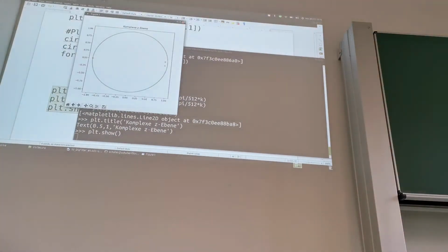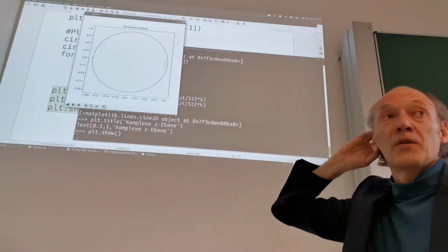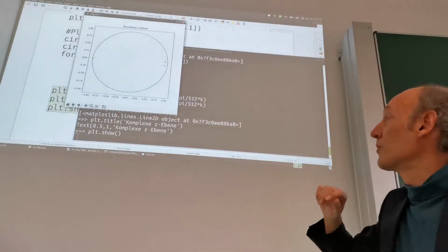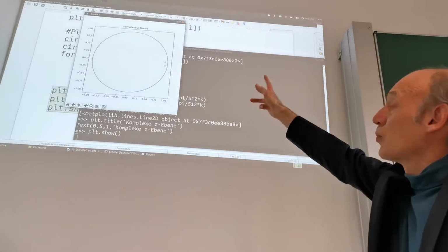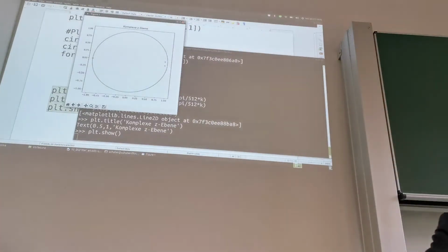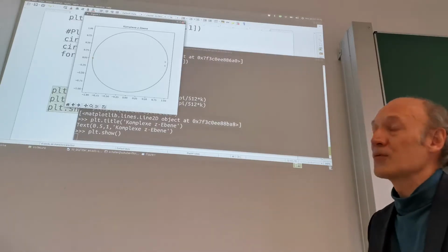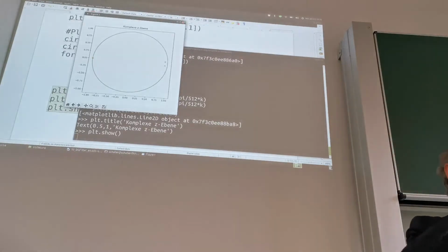Then you can see the unit circle in green, and you can see those two blue crosses, which are the locations of the poles. And you can see the two poles are indeed conjugate complex and inside the unit circle, which means this filter is stable. Right? It's not exploding. It's not getting bigger and bigger, but if you have an input and then you stop the input, it decays and goes back to 0.